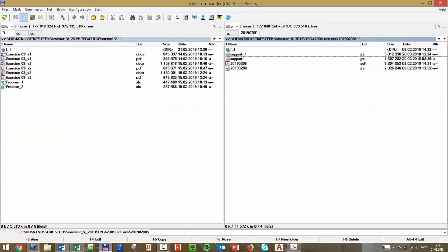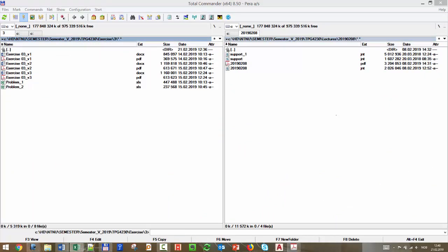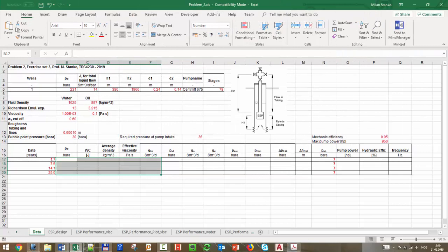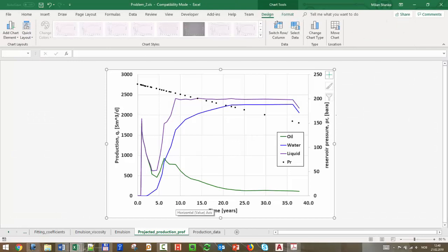So if you go to, I think we have the profile of the field in this Excel sheet. If you go towards the end, you see what was produced by the reservoir simulator. From the reservoir simulator you get the profile of oil, which has a peak and then starts to go down. Water, initially you have no water, then you have breakthrough and you start producing water. And reservoir pressure, the injection is not enough to maintain the pressure, so it will start to decline slowly. We assume here a kind of straight line decline.